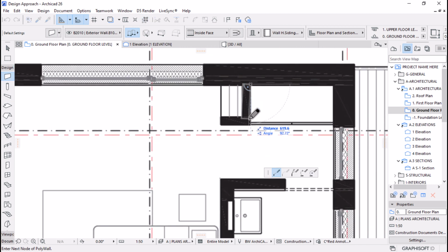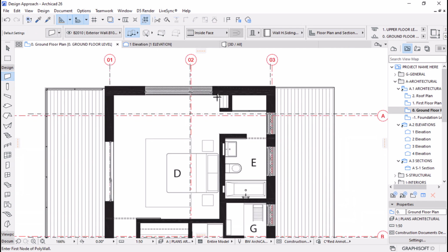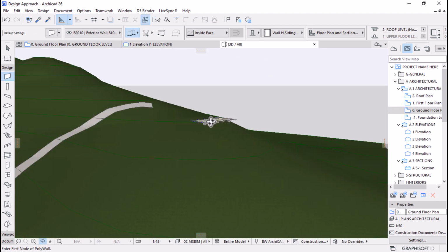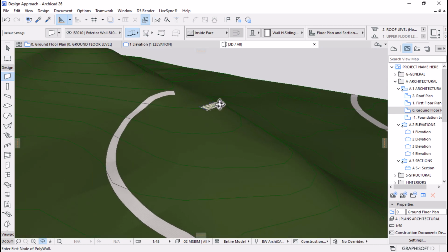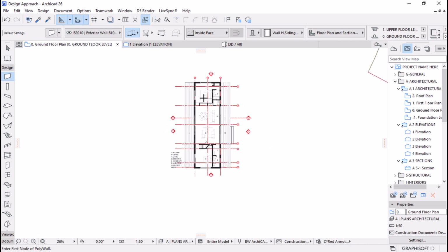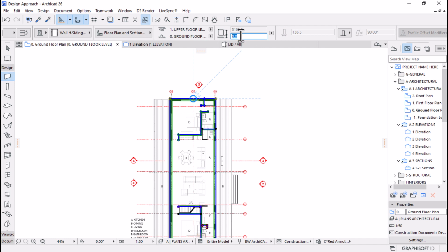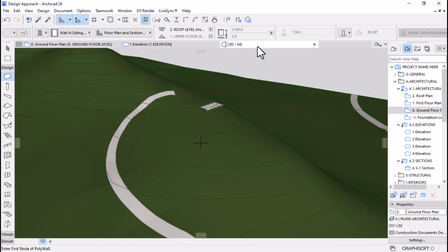We have a little set here. All right, you check on 3D because they are now at 0, and we need to set the value equivalent to our contour height. So I'll select the wall tool and hit Ctrl A to select all the elements and then paste it here, hit enter.